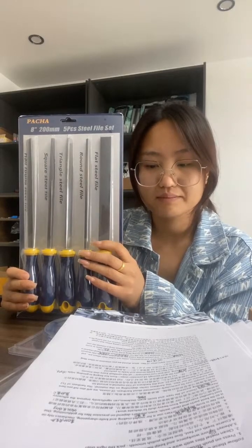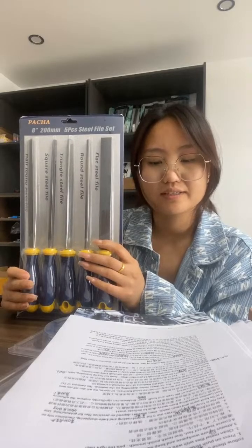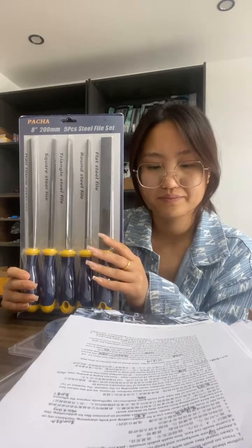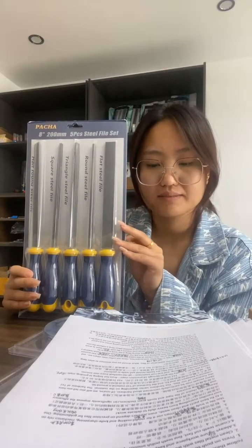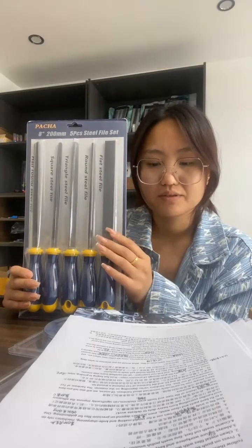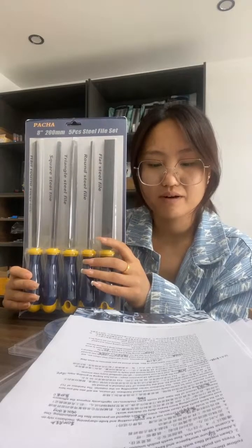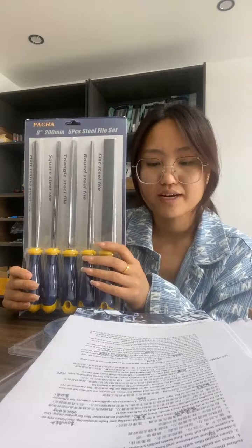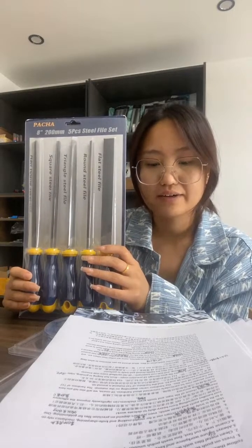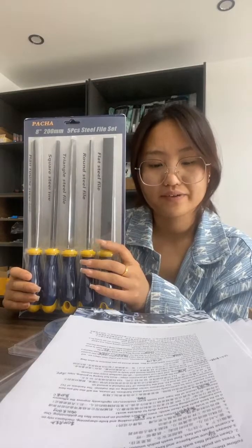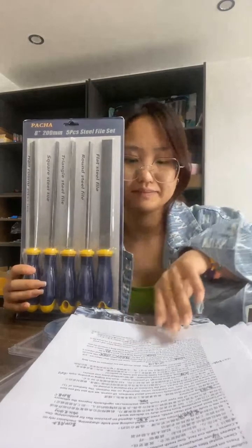When filing a material, the user can normally feel whether or not he is using the right file. And filing in the correct manner, all things being correct, a smooth cutting action and a good clean finish on the work is achieved. If there is a stubborn resistance, chances are that the wrong file is being used, the file is damaged, or the wrong method is being used.